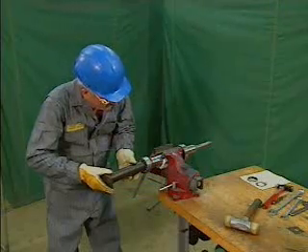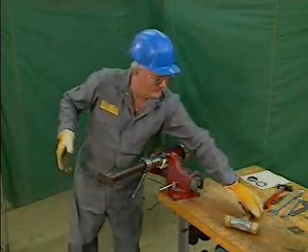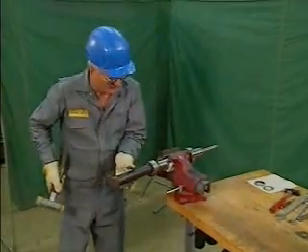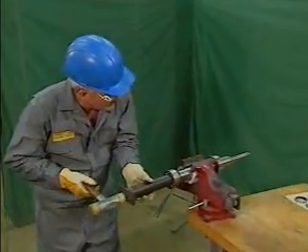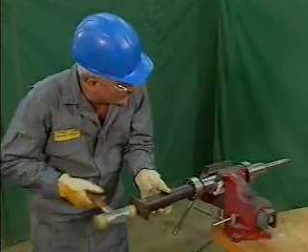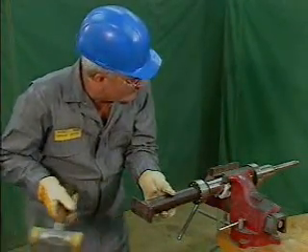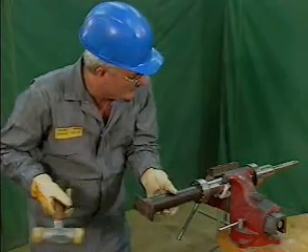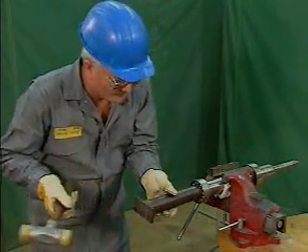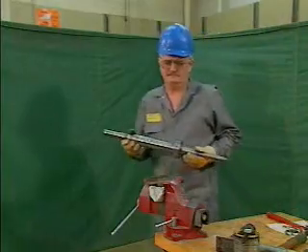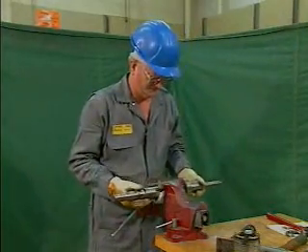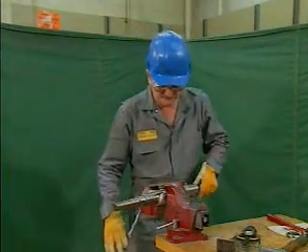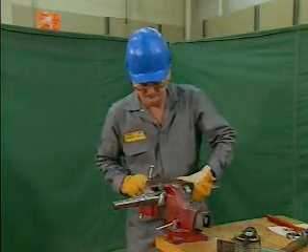When a tubular drift is used, the shaft stays stationary and the bearing is forced down the shaft. This method is generally used when the shaft can be removed from the machine and placed in a vise. If the shaft is left in the machine, its other bearings may become Brinelled. The tubular drift method is both simple and efficient. Let's watch a mechanic install a bearing using a tubular drift.